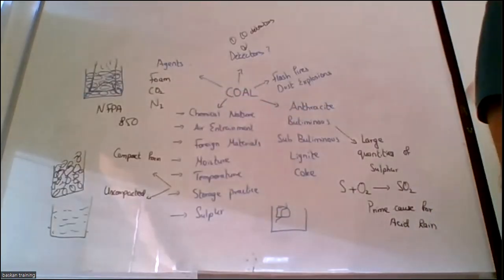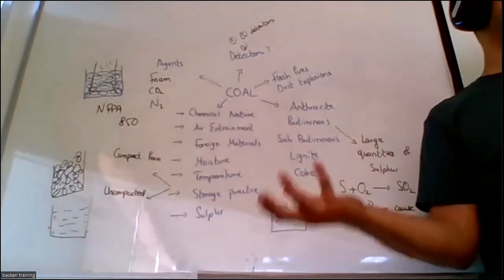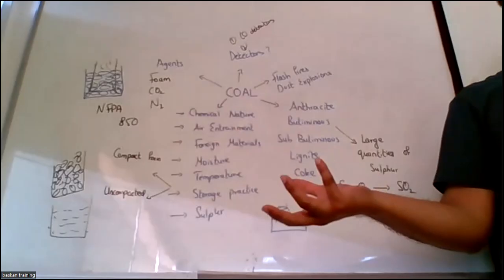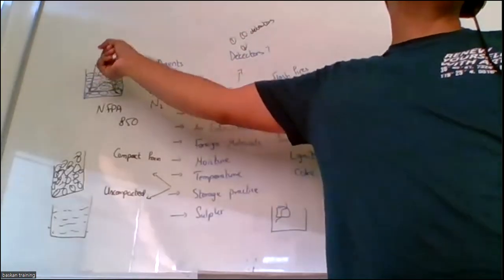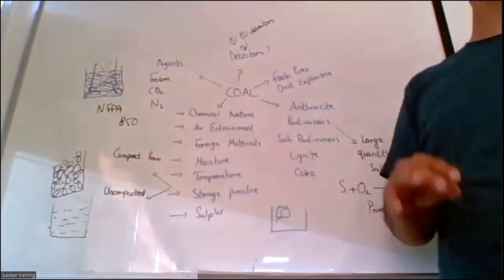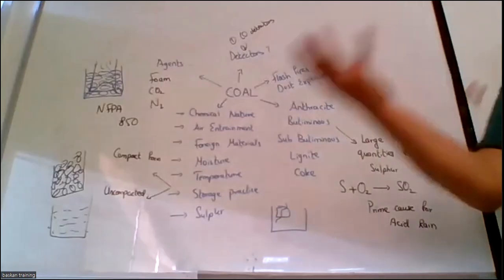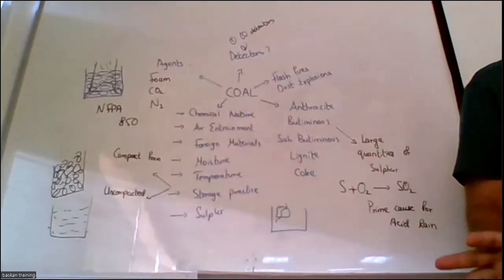Remember one thing: in coal, surface-based heat detectors are a failure. A surface-based heat detector means the temperature here has to reach 60, 65, the heat will rise, and then it will reach 57. But at the bottom, it's already 150. So by the time I get a detection, the surface-based detection has already failed. So I don't use surface-based detection here.